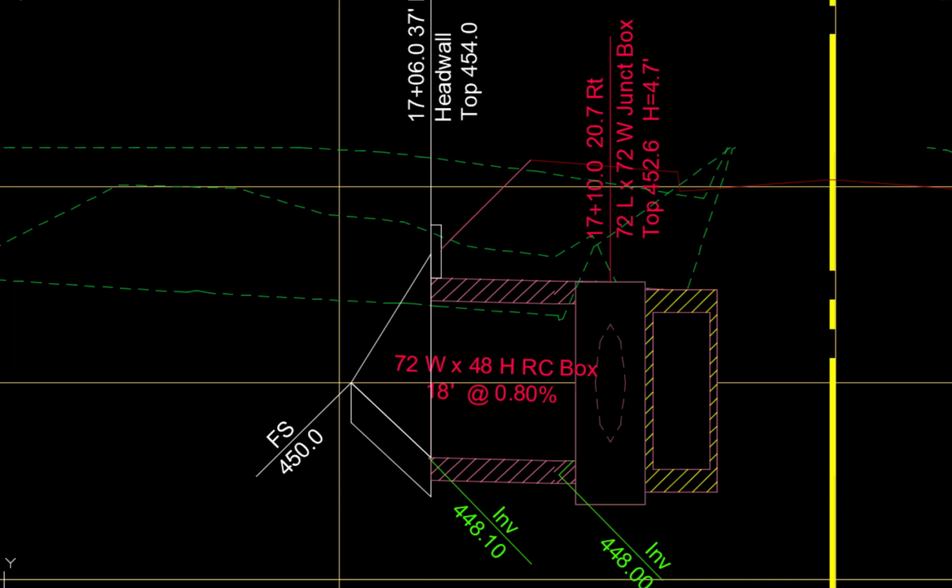To minimize the volume of concrete in the wing walls and slope paving, the wing wall footings and floor slope upward at approximately 5:1 until they intersect the sloping top of the wing wall. The dimensions and elevation of the wing walls are adjusted to an even foot that do not exceed the 2:1 and 5:1 slope parameter. The head wall and wing wall footing and face are hatched in the drawing.